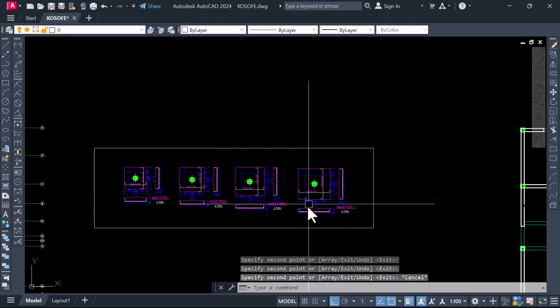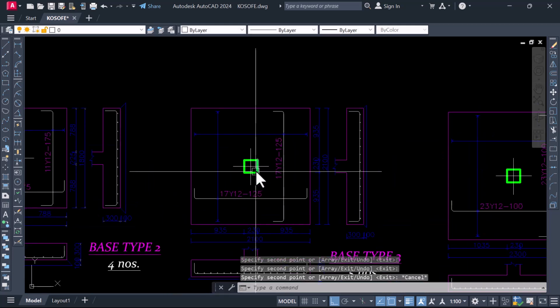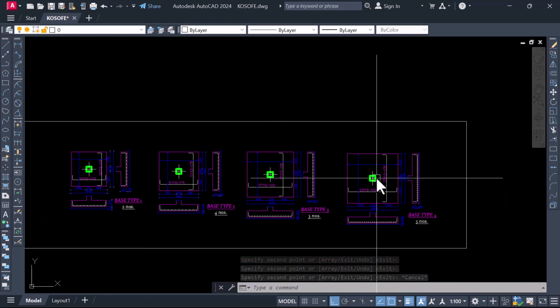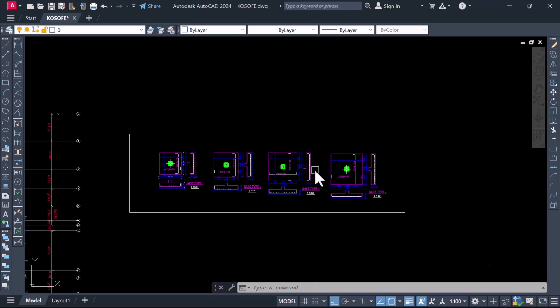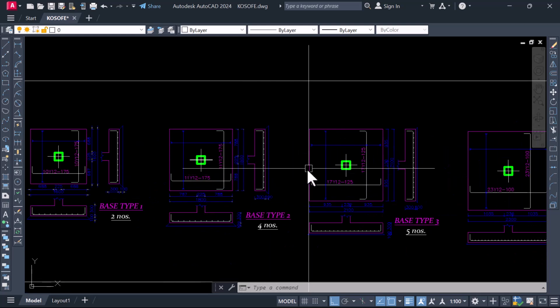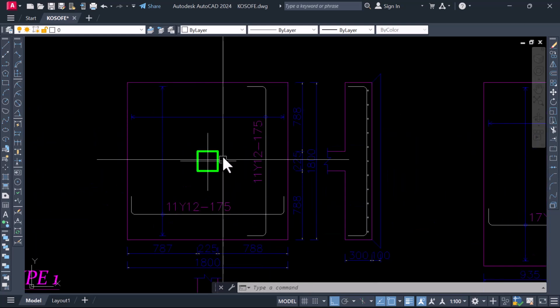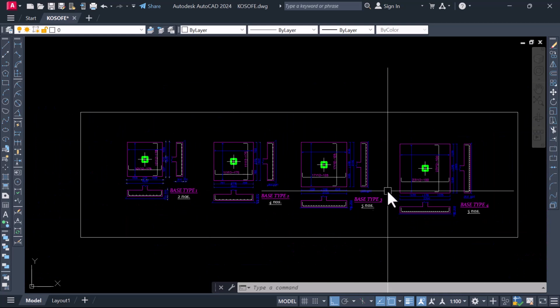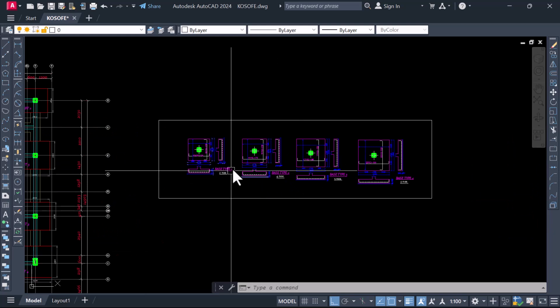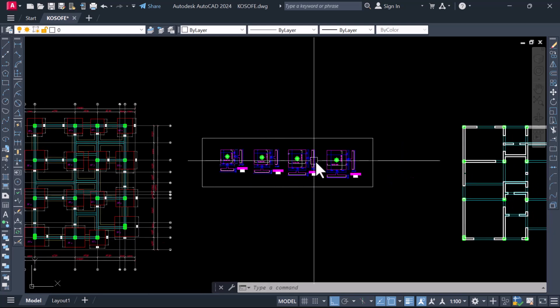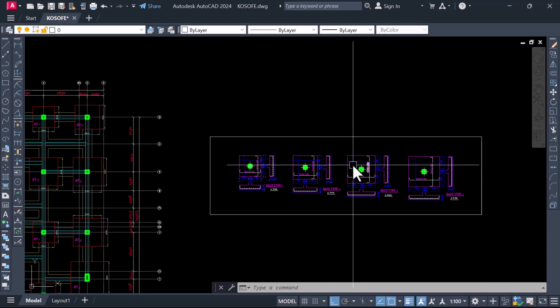This is just for easy placement. This is going to guide the iron benders on site or the engineers while doing the column set out, just to locate that they are all center to center. But if they're not center, please place it at the right position of the grid. So at this portion, what we're going to do is provide a section for the wall, and we'll be done with our pad detail for the foundation.